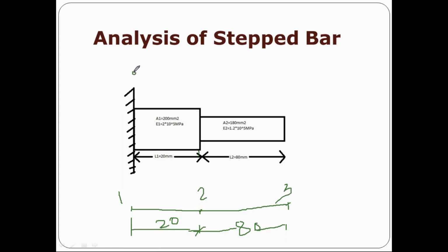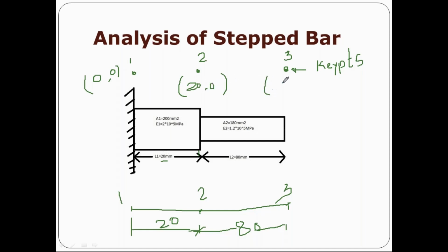So first of all you can draw points only in ANSYS, first, second, third. That is called key points. You can draw 3 key points. The first key point you can call at 0, 0, because when you are saying 20, the assumption is the first point is at 0, 0. Then the second coordinate is 20, 0. Can you please tell me what is the third point coordinate?